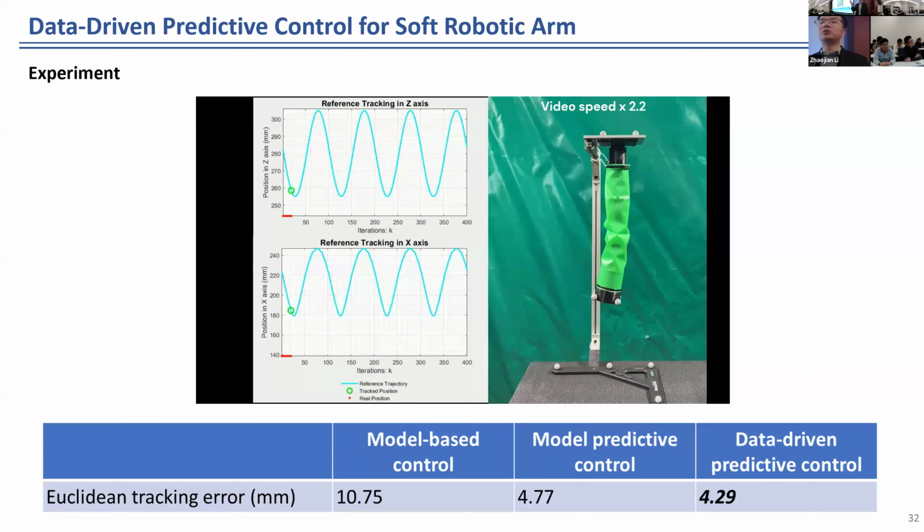But we were able to find a vacuum with really low power requirements, only around 800 watts, and we can also control the power. The previous one is AC and cannot control the power, but now we are using a DC vacuum motor. As you can see, when we need to attract the fruit and detach the fruit, we use most of the power. But after that, we can slow down the motor, and then the power on average will be quite manageable. So the previous biggest concern we had for the vacuum-based approach was the power consumption and also the space, but now we have found a good solution to address that concern.